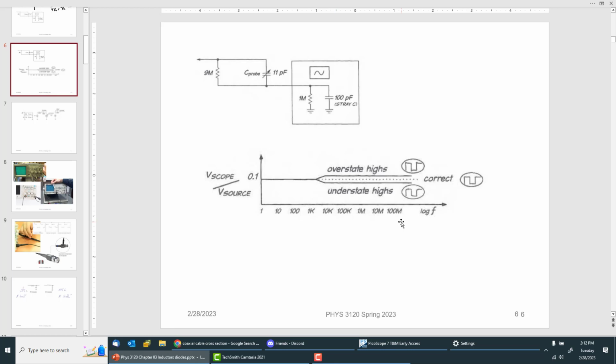The values we've been using have been picked carefully to avoid problems. But now, when we start dealing with transistors, we're going to have to deal with very low impedances. And we want our input impedance of our scope to be as high as we possibly can get it.